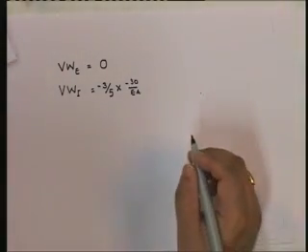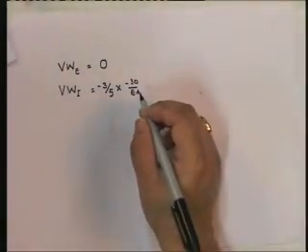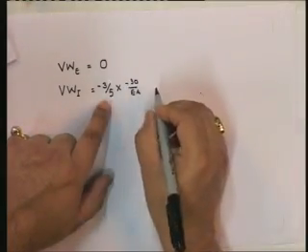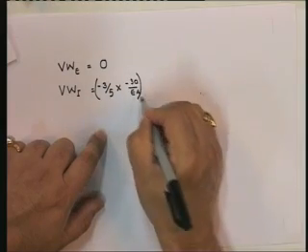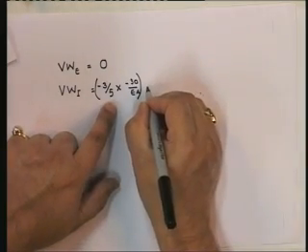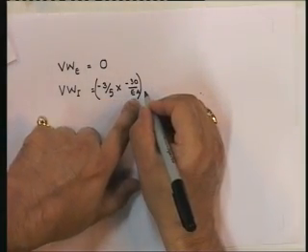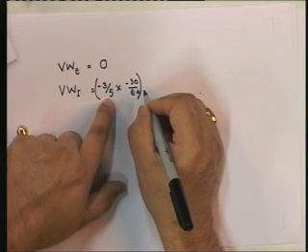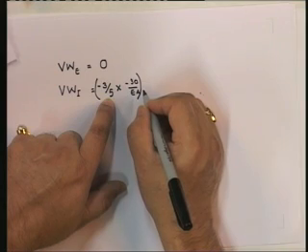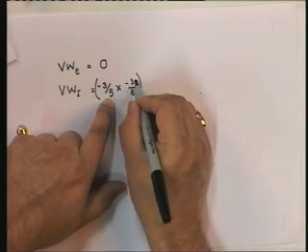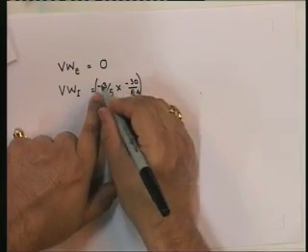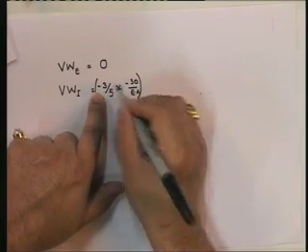So the internal virtual work contribution by AB is going to be minus 3 by 5 into minus 30 by EA. That's the virtual work done by the real deformation in AB due to the loads undergoing the virtual force in the system. This negative implies that there is a shortening. This negative implies that there is a compressive force.